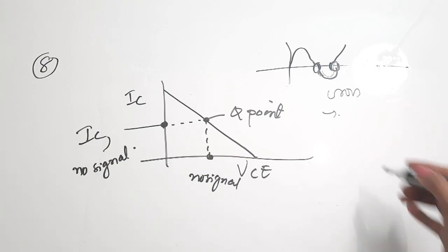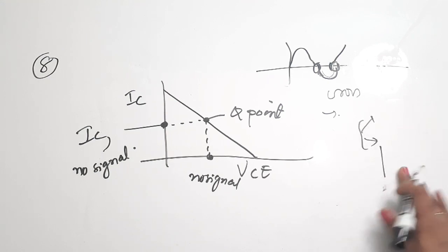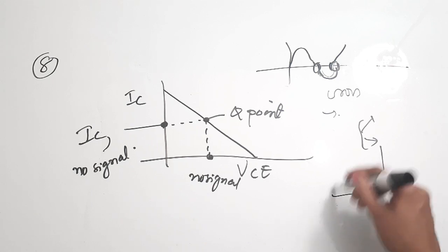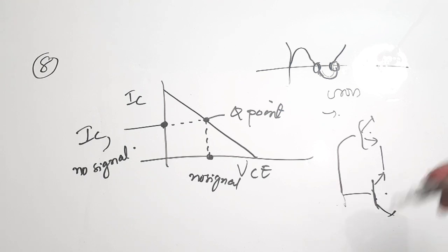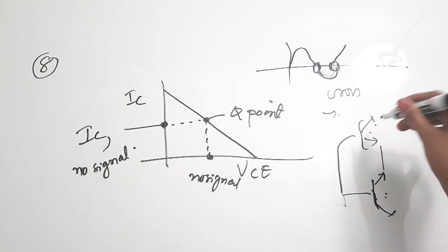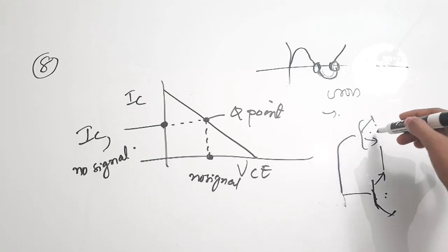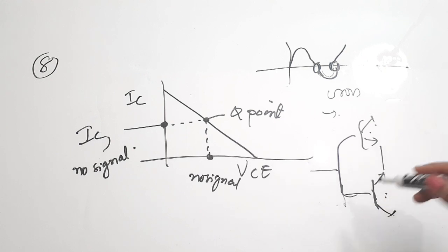So a push-pull type of amplifier means an amplifier in which 2 transistors are connected in a manner like this, and when one transistor is on, the other one is off. Next, when this is on, this one is off. So it is a push-pull connection. So what will happen here is, only when this 0.7 voltage is reached, the transistor will actually start conducting.